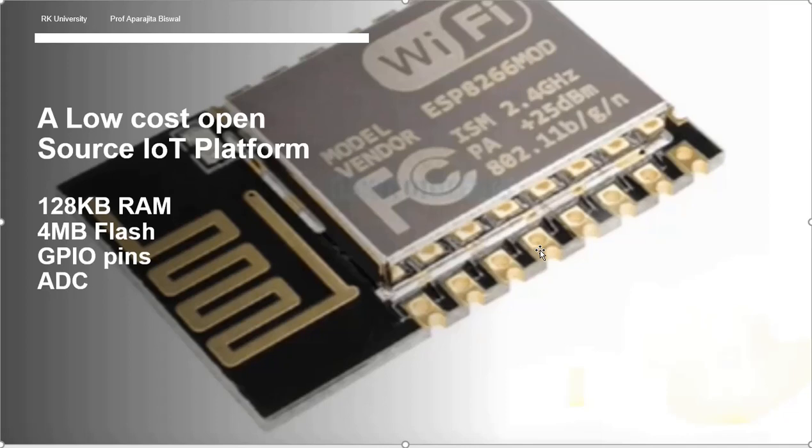MicroPython can also be used to program Node MCU. To work with sensors and actuators, the interface we need is GPIO or digital bidirectional pins. These pins are used to monitor different parameters like temperature, humidity, etc. GPIO can read sensor data. It can also write digital signals out. We can control LED, motor, servo motor, etc.